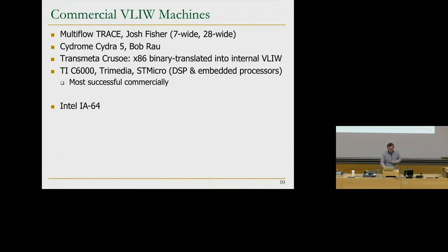But this is very different in the sense that you can pack completely unrelated instructions that are doing different things on different data. So actually, one of the processors, Transmeta Crusoe, was an x86 processor, and it had this compiler that translated the x86 programs into an internal VLIW format. So internally, they were executed as they had a VLIW engine. This was very, very interesting. They wanted to compete with Intel and AMD in terms of the speed of the x86 processors, but the overheads of doing this translation were not negligible. As a result, they didn't succeed, and I don't think they're around anymore.